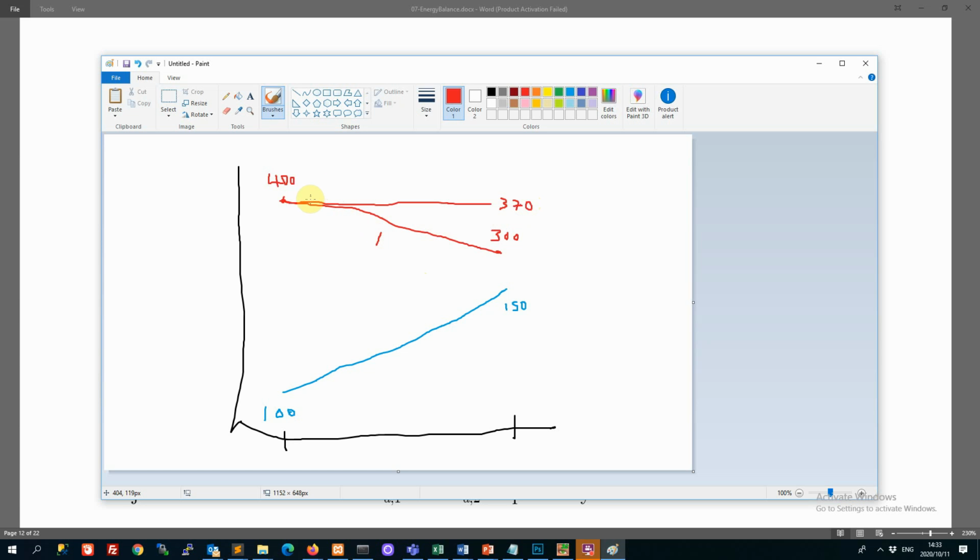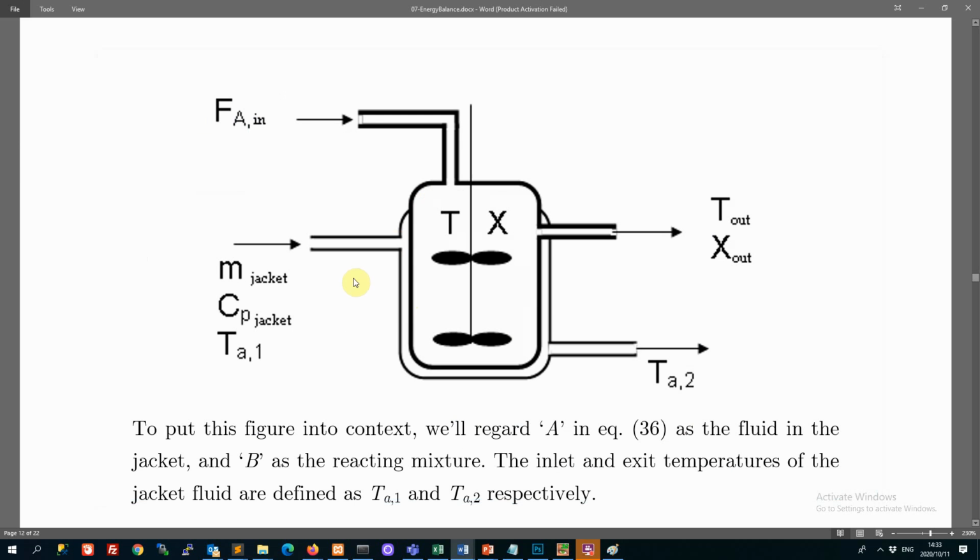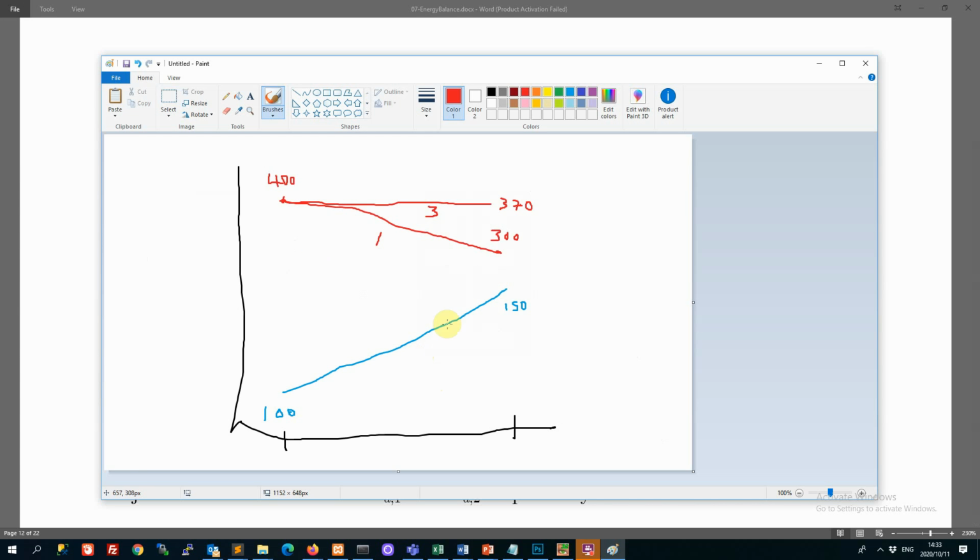So if you apply a higher flow rate, then of course you are still giving up heat, but because you are pumping at a higher flow rate, let's say 3 tons instead of 1 ton per hour or whatever it is, if you are pumping oil faster through here, then the oil would be at a higher temperature, and there would also be a higher rate of transfer.